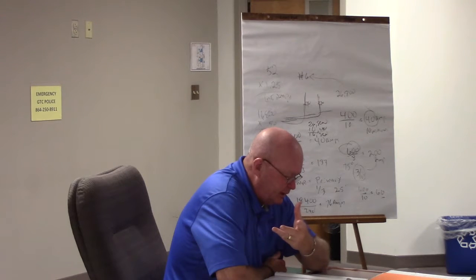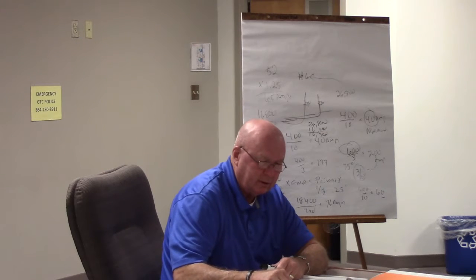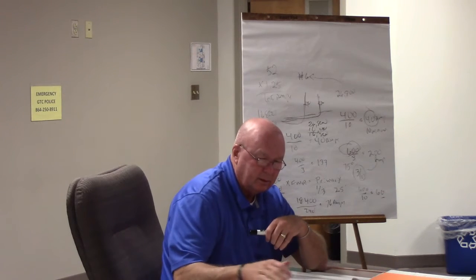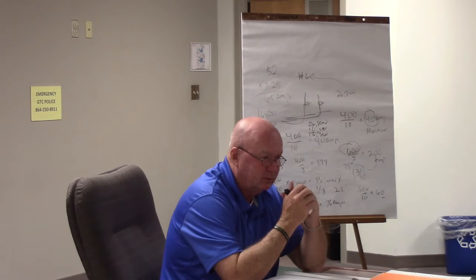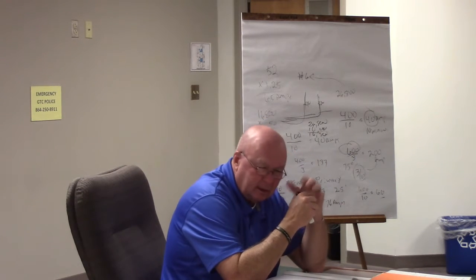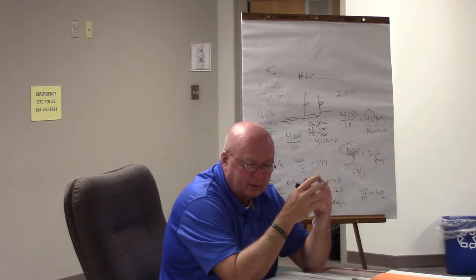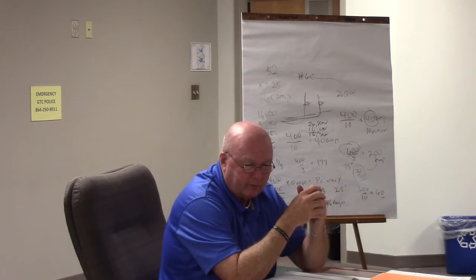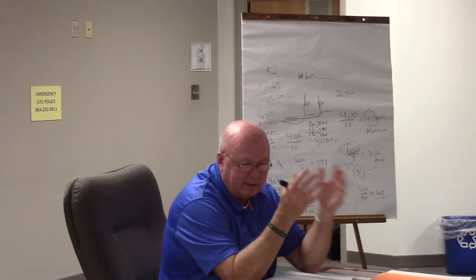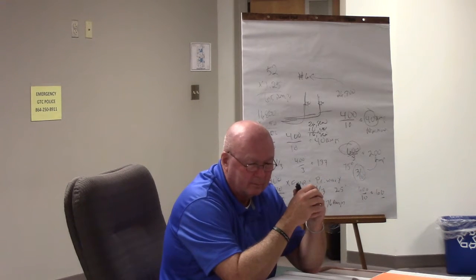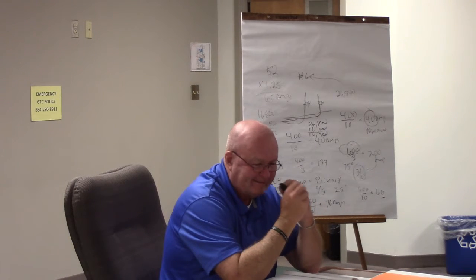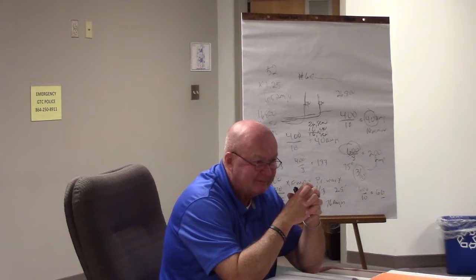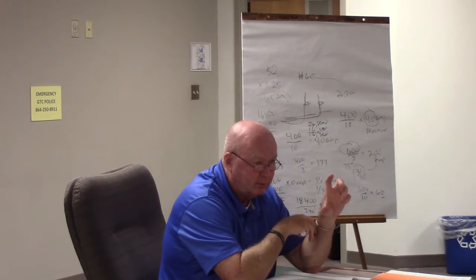The last thing I want you to see is lighting loads. 220.12. If you turn to code book 220.12, there's actually a table. And it gets into lighting loads. As a matter of fact, the heading is general lighting loads by occupancy. And for example, like in a dwelling, it's how many VAs per square foot for a dwelling. Table 220.12, the big table, 220.12.